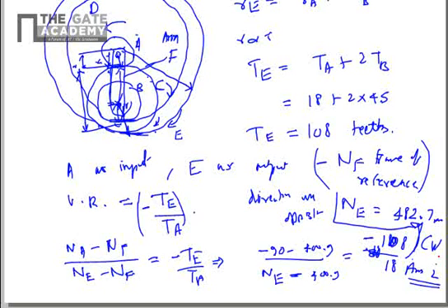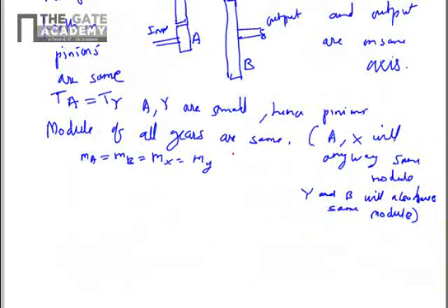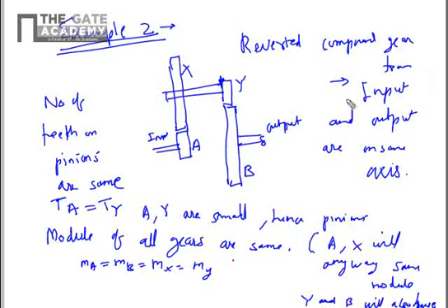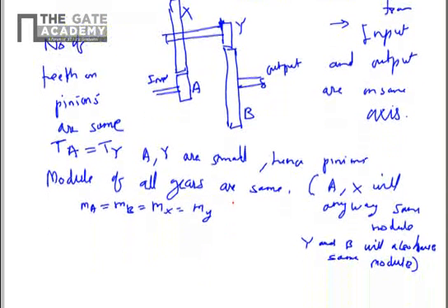So by use of such complex epicyclic and compound gear trains, you can get very typical values of gear ratio. So that is the power of such trains, and they are used in some special applications, particularly in wall clocks, the mechanical wall clocks. You want to get some specific gear ratio in some confined space, which is not necessary for a compound epicyclic chain. So this chain can have a different module, this chain can have a different module, but this is given in this present problem.